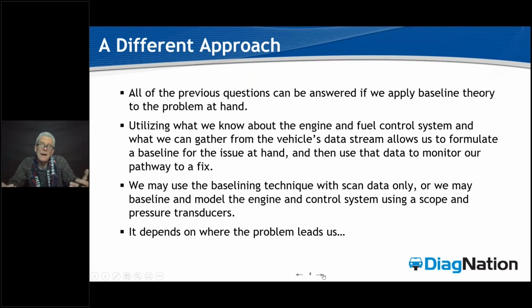And as in the independent aftermarket, we don't have brand new cars per se to go pull off the lot and get those readings. We learn our baselines through before and after cleaning, looking at the data before we clean the car versus after we clean the car. Assuming that we did get the deposit down to a manageable level, we're going to call that our clean baseline in the independent aftermarket, and then start to build some diagnostic thought and some diagnostic data from that information that can really help us when we're going after these weirdo problems, right?